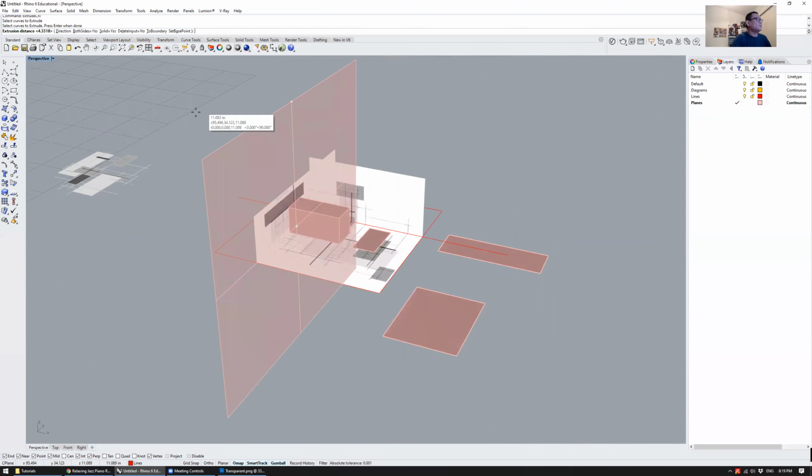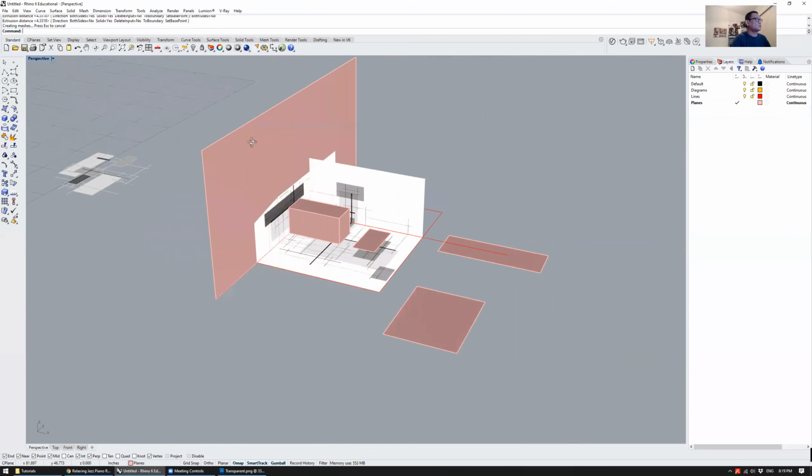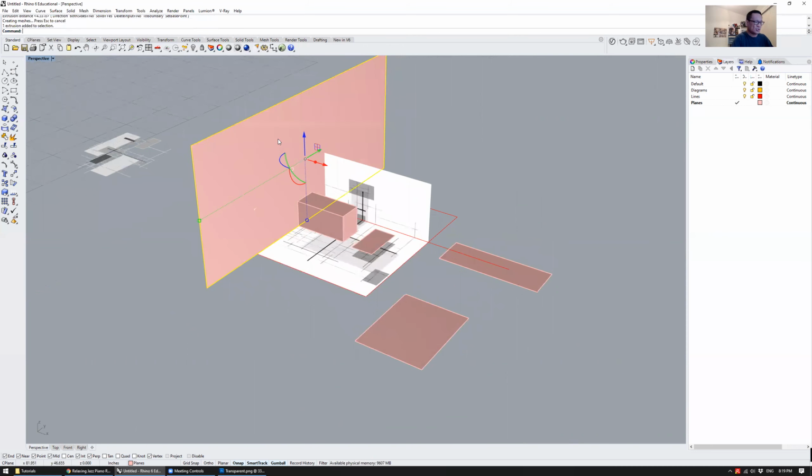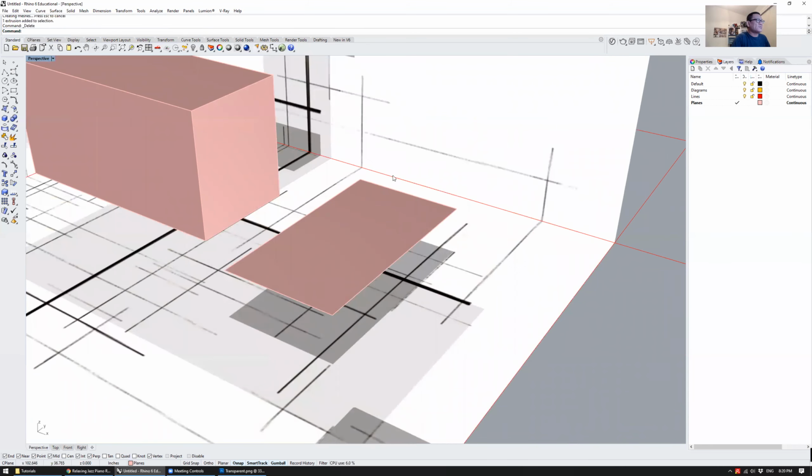When I extrude it, you might have slightly different settings. I have different toggles on, Both Sides is on, but you can basically make a giant plane, right? It will extrude out a giant plane in one direction or other, okay? But you can also use it on the edges of surfaces as well.